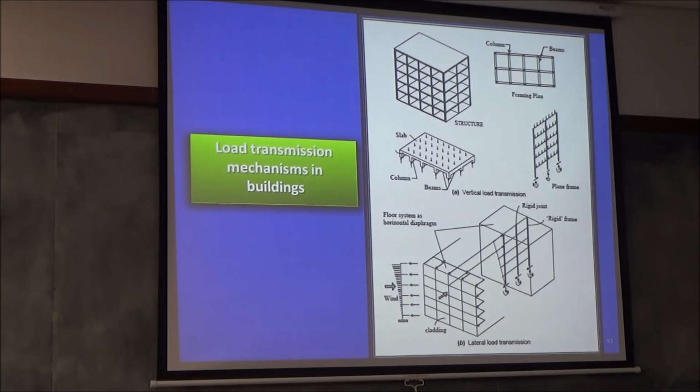What's your question? So the relative stiffness is. No, there's no stiffness here. There are 3 approximate methods. One is called the portal method. Second is called the cantilever method, where you don't make these assumptions. There's a third method called the factor method. The factor method is more accurate, because you're bringing in relative stiffnesses which you didn't bring in the first 2 methods. So if you want more accuracy, do the factor method. Question clear?